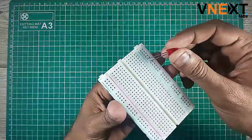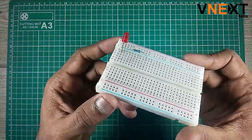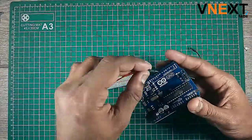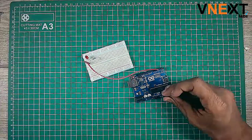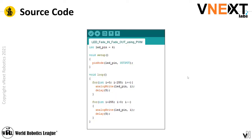For the LED, you might be aware that the longer leg of the LED is positive and the shorter is negative. We are going to connect the positive side of the LED to digital pin 6 via the resistor and the negative pin to ground. This is how the overall circuit looks.